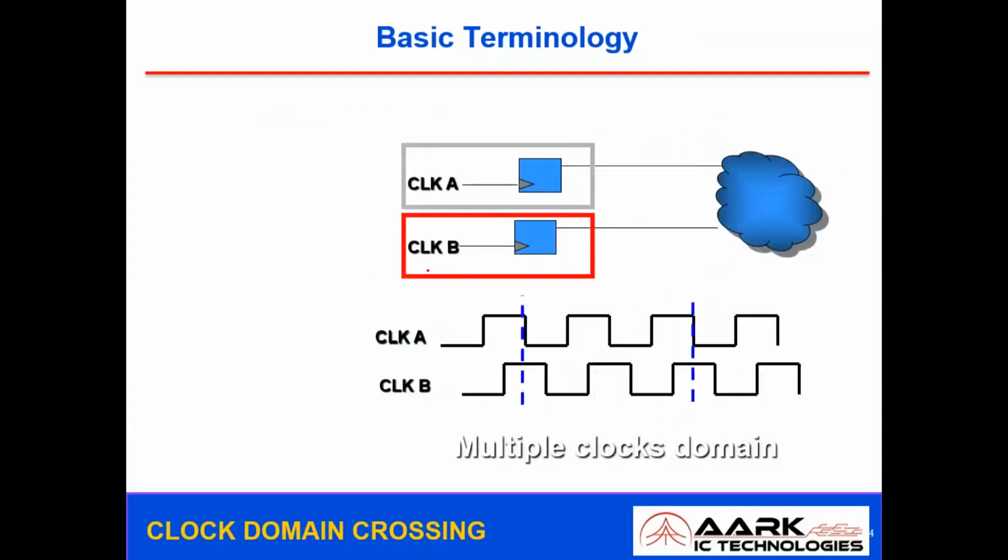When we go to multiple clock domains, it is completely different. Now the same combinational logic is triggered with clock A, and let's say it has a frequency of f1, say 10 hertz or 10 kilohertz. And if this other clock is operating at some 10 megahertz, and these two clocks are used for this logic, that means this combinational logic is going to be triggered at one particular edge by this clock, and at another particular edge by the other. Here it is triggering at this point, and at the same time this is somewhere else.